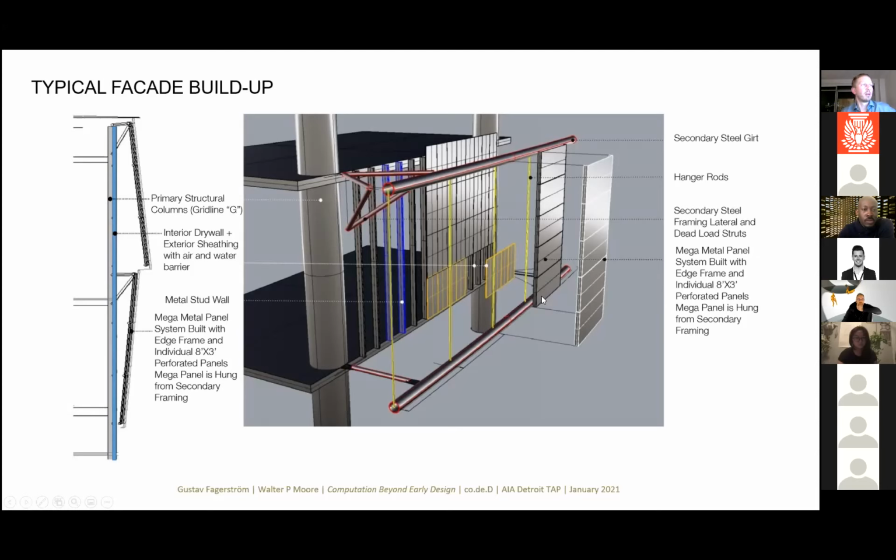Then the lower end of the panels are pinned. It's a little bit hard to see in this view, but you'll see that later on the mock-up picture. So these struts are pinned so that whenever the wind blows, the lateral forces that affect the building get transferred back here, but any self-weight is taken up, including the weight of the lower hoop, by these hangers and goes back through this hoop and back through these gravity connections.